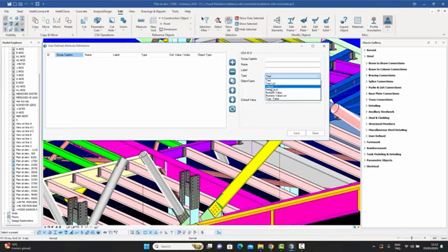But if you also want it to be specific integers only, like you want the value of that particular attribute to be, say, either 1 or 7 or 15 and nothing else, then you would use the integer list, in which case you will specify what those integers are, and then the user will select from only that list. And similarly, you have the floating point values or a floating point value list, which we call a numeric value or a numeric value list. Or the last option is that it could be a Boolean type, so it could be a true false type variable.